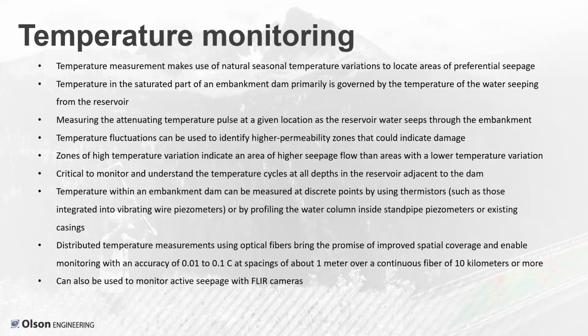The expectation being that there is a temperature differential between the water that's impounded in the reservoir of the dam and the dam structure itself. And there are a couple of different ways that we can measure this. We're looking for high variation in temperature, but we can do this either with temperature sensors that are on the surface or down in holes to look at temperature variations.